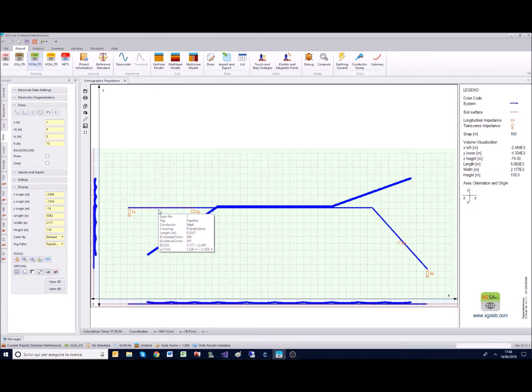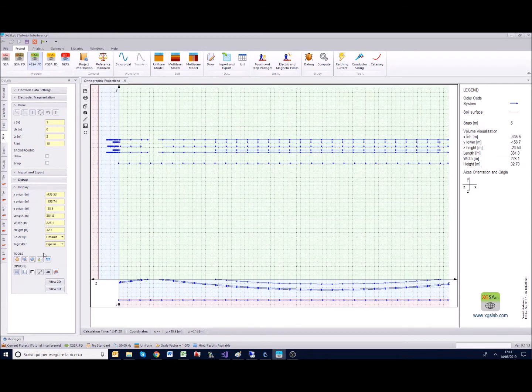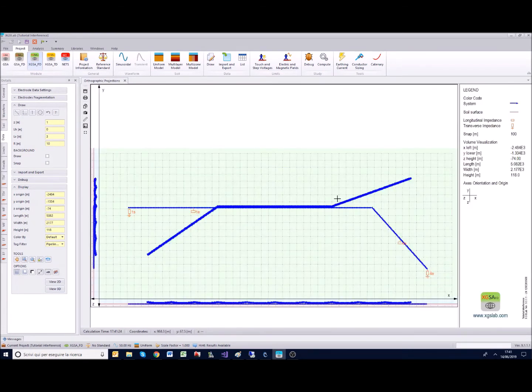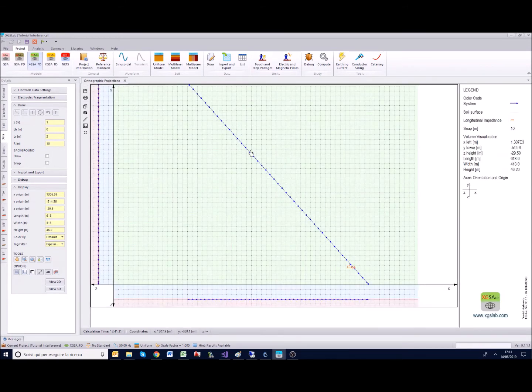For example, all the spans are ordered, as you can see, span number 1, then span number 2, then span number 3, and finally span number 4. Moreover, the condition also wanted that the orientation of the consecutive spans were consecutive. So, as you can see, the order was exactly this, and also in this case the order was continuously coherent and had to be this. So basically the main problem was that if you had to modify a long pipeline in a central part by deleting and redrawing one span, you had to redraw the completed pipeline.